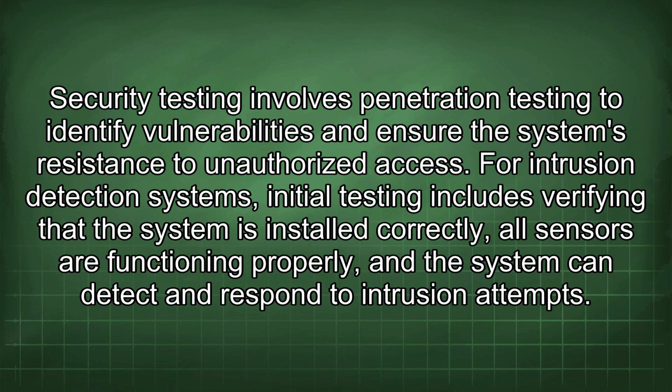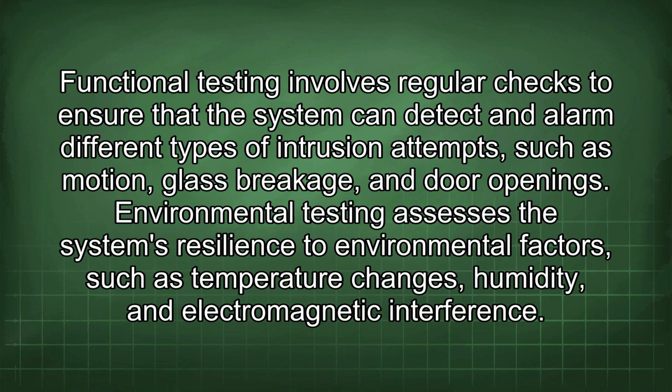For intrusion detection systems, initial testing includes verifying that the system is installed correctly, all sensors are functioning properly, and the system can detect and respond to intrusion attempts. Functional testing involves regular checks to ensure that the system can detect and alarm different types of intrusion attempts, such as motion, glass breakage, and door openings. Environmental testing assesses the system's resilience to environmental factors, such as temperature changes, humidity, and electromagnetic interference.